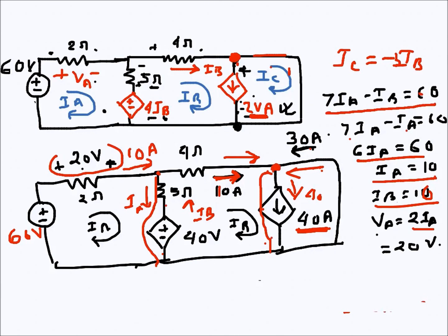So this is 0, and if we look at KVL in the first loop, this is 60 here, 20 here, and 40 here, so 60 rise, 20 drop and 40 drop, so that's 60. Even in this branch, this is a 40 rise here, and this one is 4 ohms and the current is 10, so again rise 40 and drop 40 here, so KVL is satisfied in the second branch as well. No drop here, and these two are virtually a short circuit. So that's all.